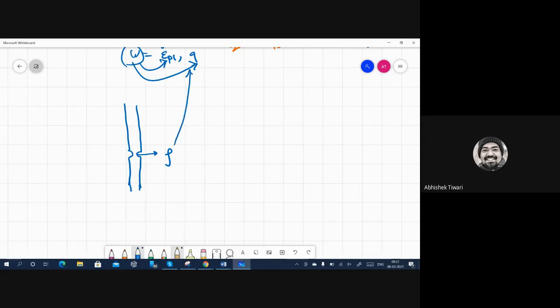So what you can do is simulate a simple tensile specimen with some amount of root radius. So it's basically a U notch, and you do an elastic simulation and find out the value of Q. And you will see in most of the area here, although Q will have a variation here also, but not too much.